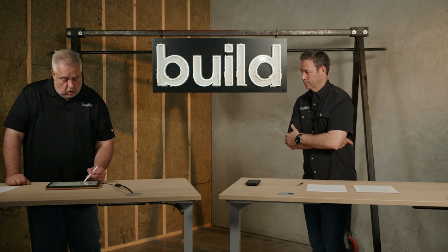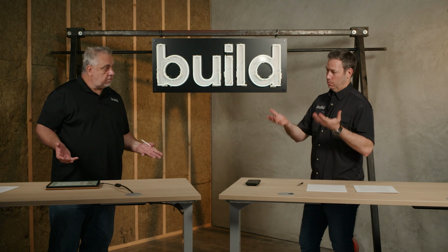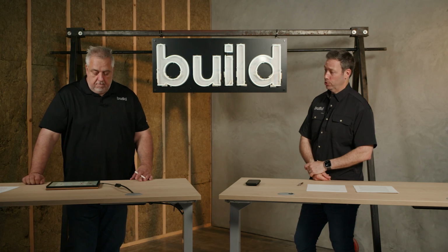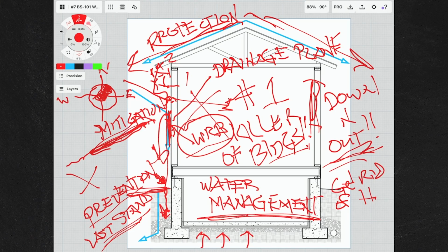So you have to worry about the water coming down, but you also need to worry about hydrostatic pressure of water coming up, building up against that foundation, and that pressure, that hydrostatic pressure, could turn your basement into a submarine. Yeah, definitely. And the whole idea of prevention down here, basically what we're trying to do is prevent water from going into our basement and having it flood.